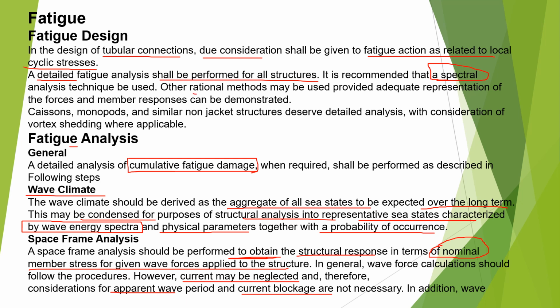Other rational methods may be used provided adequate representation of forces and member response can be demonstrated. If we can demonstrate adequate representation of forces and member response, which will be displacement and so on, but mainly we are interested in getting the stresses. As you see here, mainly we are interested in getting the structural response in terms of nominal member stress for a given wave force applied to the structure.